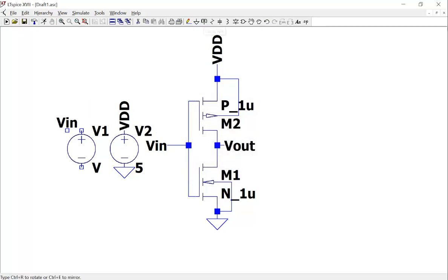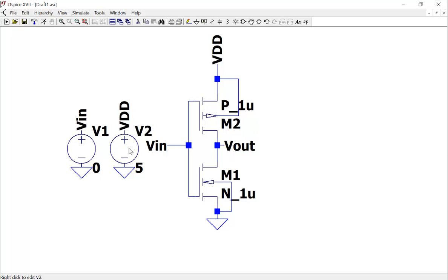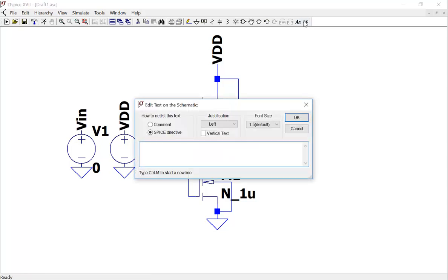Right. So I'm going to sweep it, and I'm going to ground it. So this I give a 0, and I'm going to do a DC sweep for it. So I want to use dot include. Let's do a DC sweep first. Is that V1? V1. Do I need a 0? V1 from 0 to 5 volts.